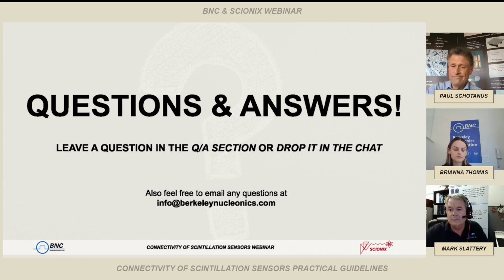So it's not really, you're talking about measurements. Yeah, well, I don't think really it depends what you want to do with your signals. If you want to get fast signals out of your SiPM detector, you need anyway an amplifier chain with a low resistor value in order to get the minimum rise time. I mentioned minimum rise time of a SiPM of, let's say, 1 square centimeter is roughly a few tens of nanoseconds. So it depends on your application. Okay.